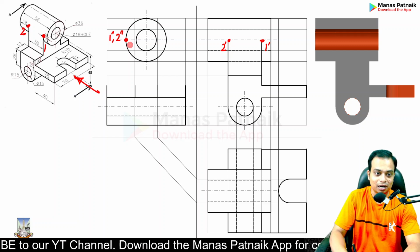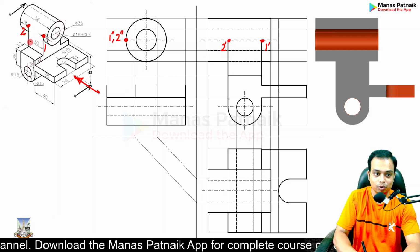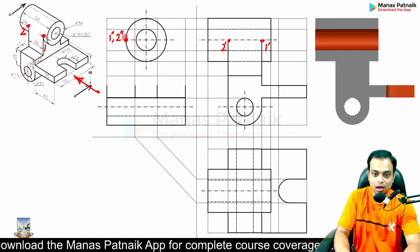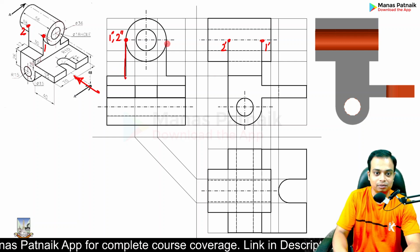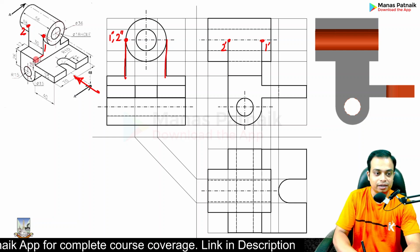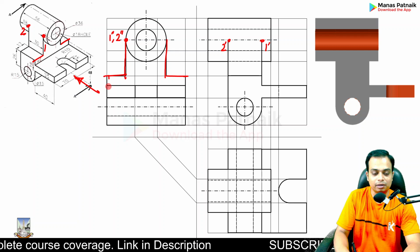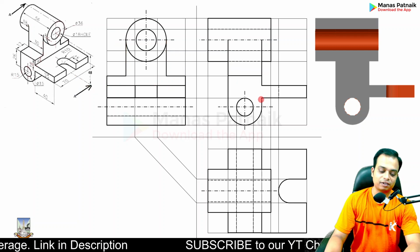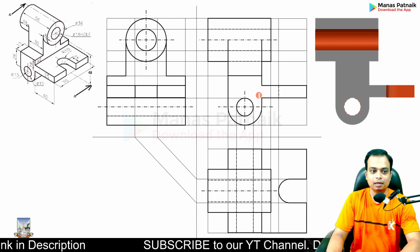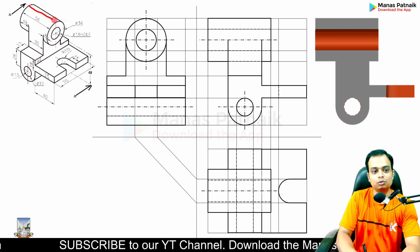So you need to come downwards 30 mm below. This distance we know very well, it is 30. So you can take this line as the reference. Come 30 down, then this way to the extreme left, this way, this way, this way, and then you can obviously close it down. And finally, as far as the section is concerned, let me talk about it. What we really want is the portion of the cutting plane. Cutting plane passes through this section line.